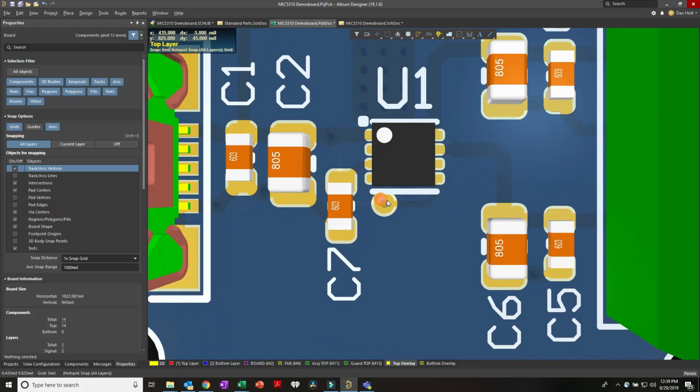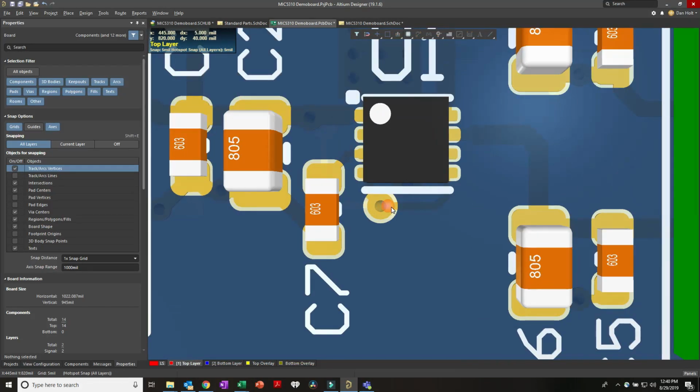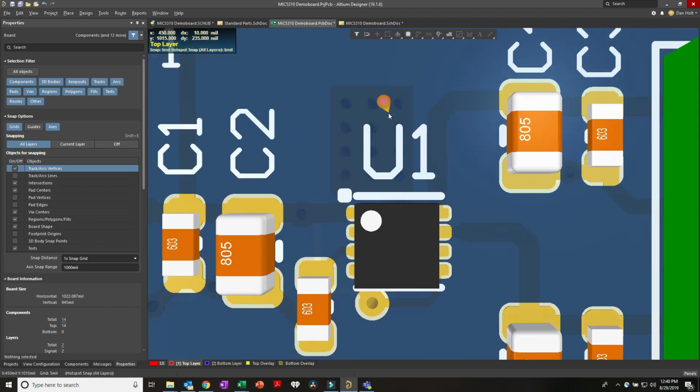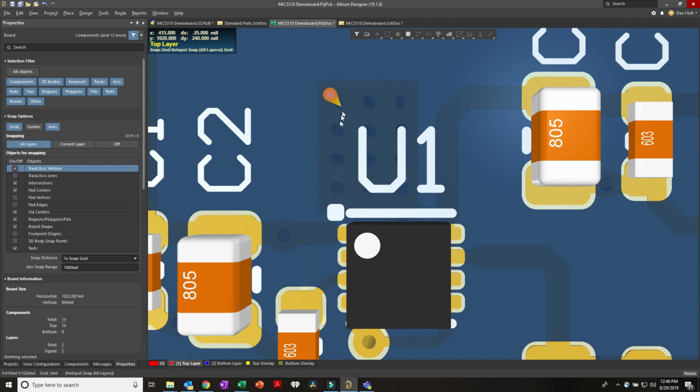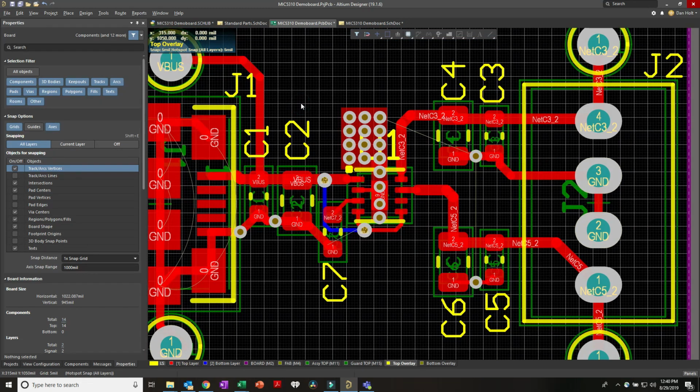So if we go to tenting, we turn the tenting off, and then go back to press 3, you can see how the tenting, the solder mask, will not be there. Which on a via, it really is no big deal. It makes it nicer to probe. On an array like this, for better or for worse, it's not there. Let's say because this is a heatsink, you didn't want to have the solder mask on here at all. You wanted this exposed so it could radiate better. You actually can just place a solder mask keep out.